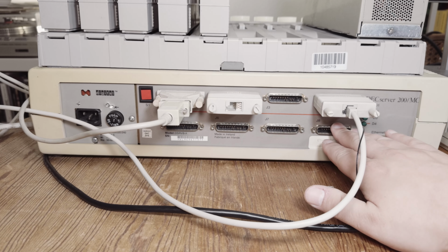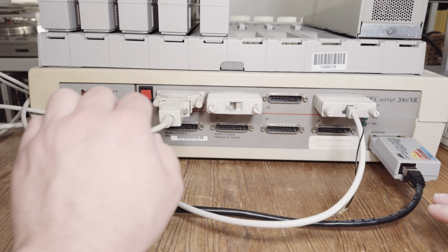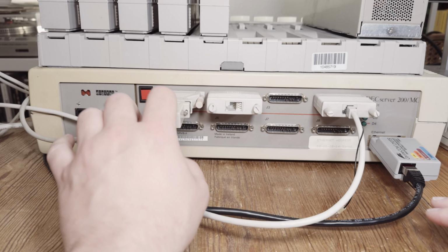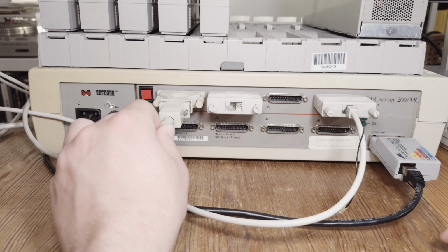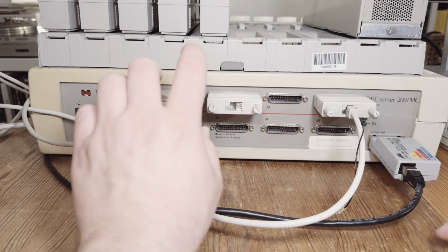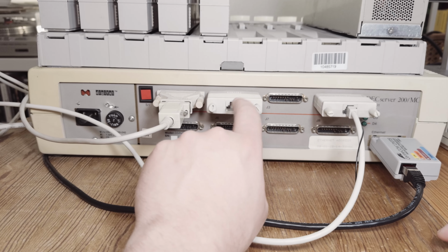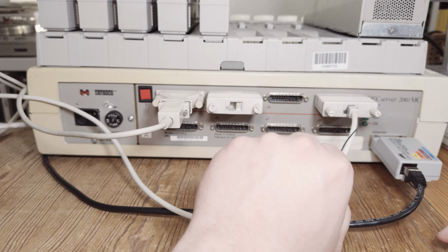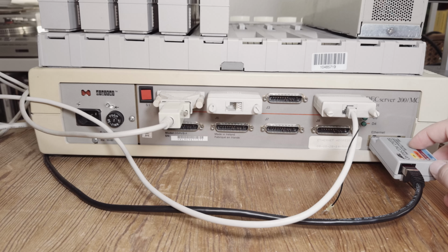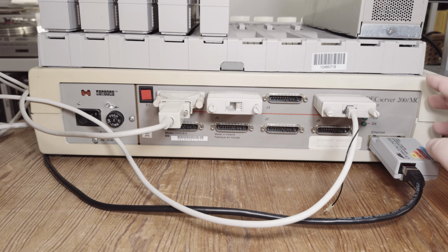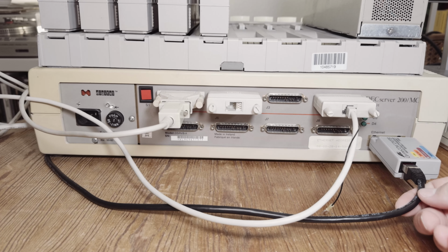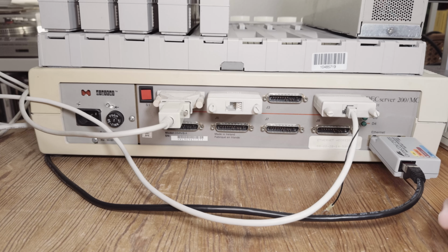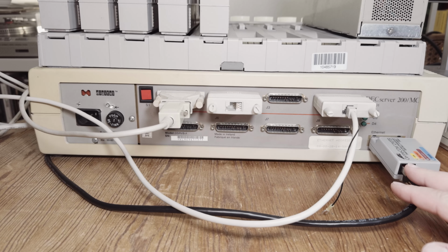Basically, you have 8 serial line connectors. You can use an adapter from 25 pin to 9 pin, and then use a null modem cable. Or you can use these DEC adapters to adapt it to an MMJ DEC style connector. And it is connected down here a transceiver which converts the AUI to 10BASE-T, which goes to the DEC repeater 90TS on the top.